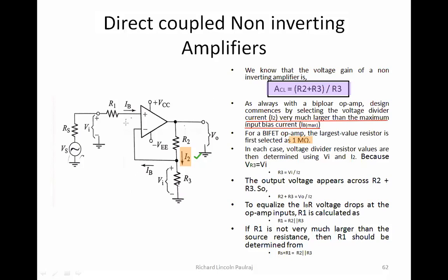Okay, so that's because whatever the voltage is at the non-inverting terminal is replicated at the inverting terminal. So you have the same potential coming through. So Vi will also be the same here, and ground is common. Fine. So we have R3 equal to Vi divided by I2, since V is equal to IR. I have voltage as Vi and current as I2.